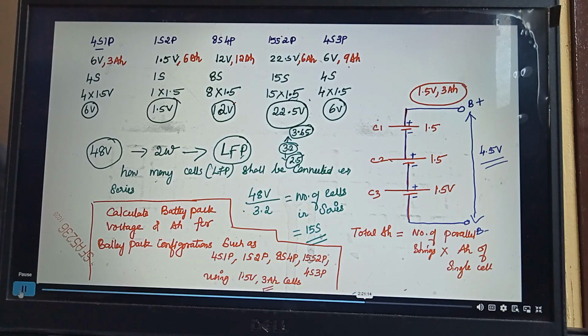Okay, so is it clear, everyone? How to find the voltage, the configuration is given. They don't ask you segments of machine. They'll ask you 15s4p using LFP, that's it. The LFP is a 6 Ah cell, that's it. But whenever it is LFP, you need to understand it's normally 3.2. They never tell you the nominal.